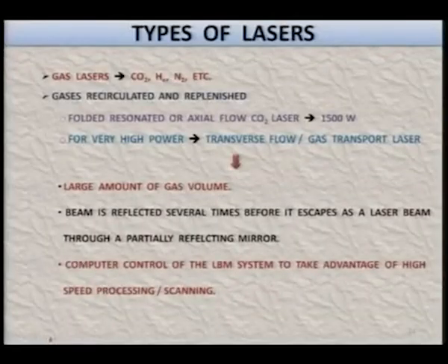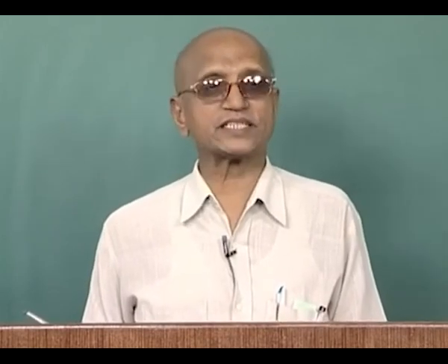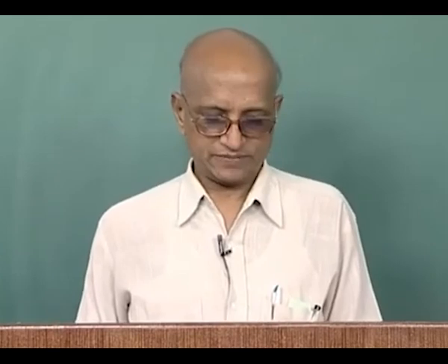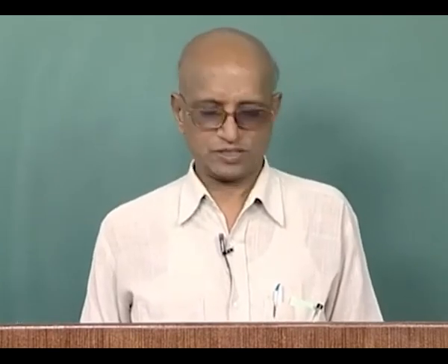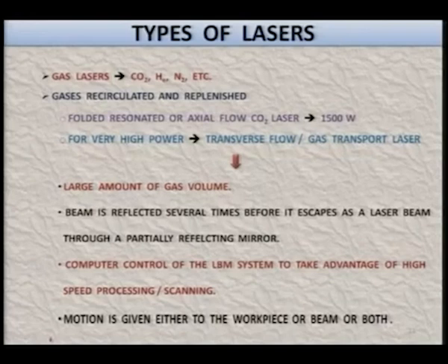Computer control of the laser beam machining system to take advantage of high speed processing scanning. All the laser beam machining setups practically are computer controlled, and this is very much essential, so that you can take advantage of high speed processing using the CNC features of these machines, that is computer numerical control feature of these machines, and motion is given either to the workpiece or to the beam, or in some cases you can give the motion to both of them depending upon the workpiece requirement.